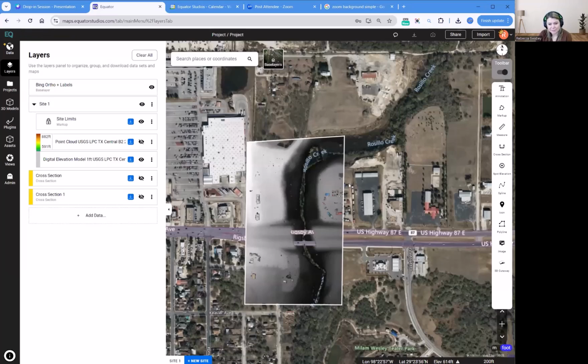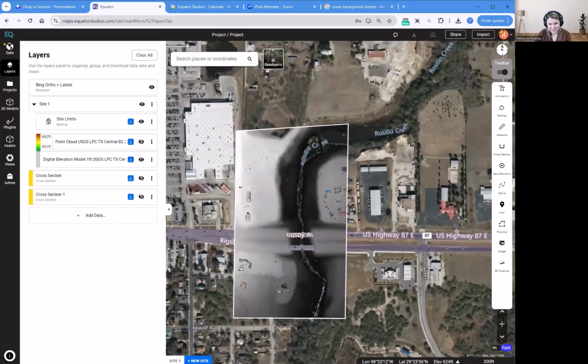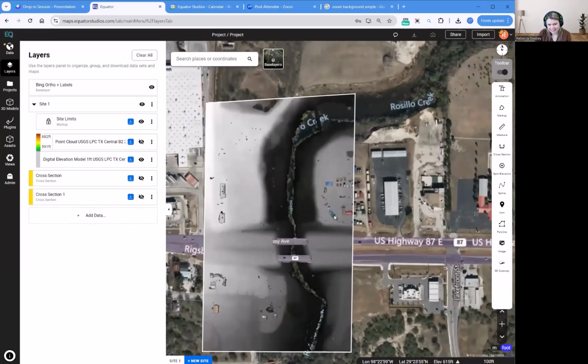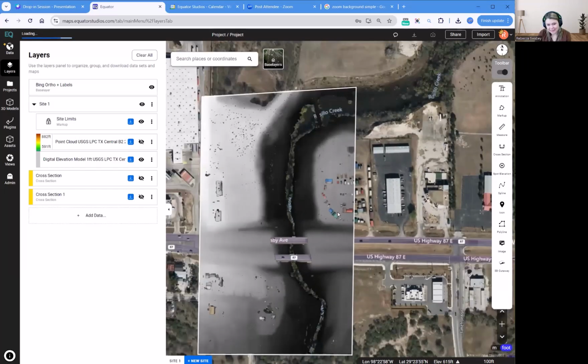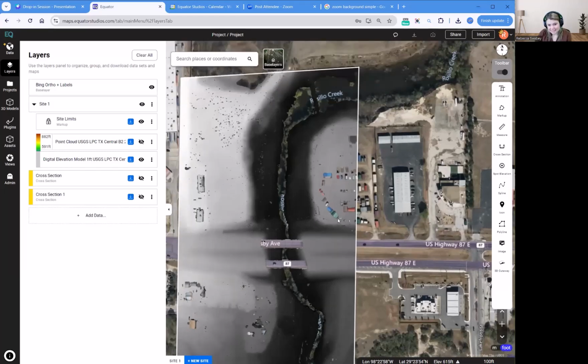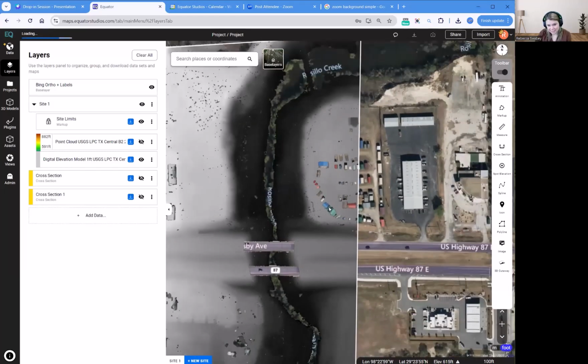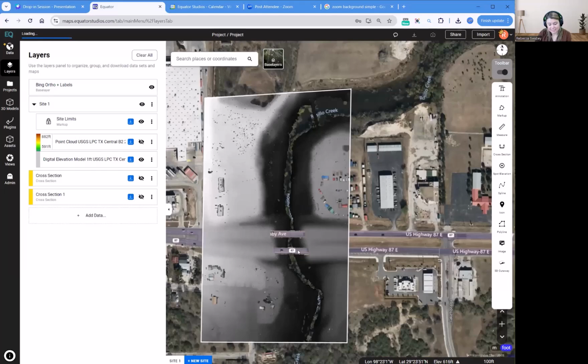One thing I'm going to say, I'm a little embarrassed to say this, but I'm going to say it just so that you guys are aware if you're going to use this right after. You can create a DEM and in the areas where there is vegetation or structure, basically non-ground points, in this DEM that I just created, it actually didn't use them. So it has a bunch of holes in it, which probably you don't want a DEM with holes in it.